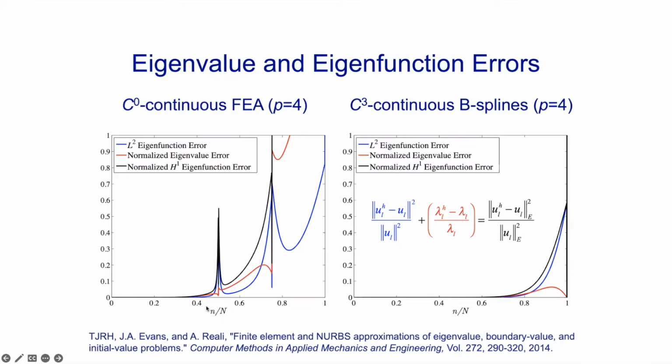And as a result, this really explains why the finite element method has never been successful with higher order elements for hard problems. You do hard problems like crash dynamics or blast type calculations. We have hyperbolic equations. You ping those high modes. Those errors are introduced in these high modes and they never go away.